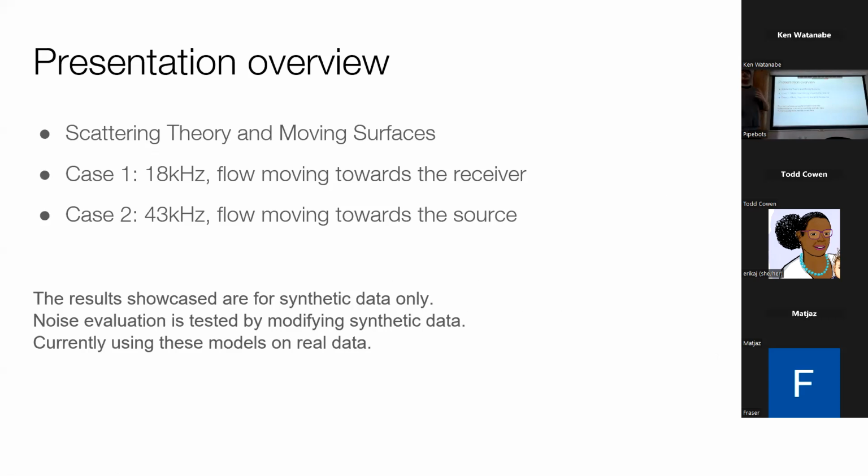So I'm going to peel back the H kernel and show a little bit of what that is. It's a big integral. And we have 2 cases. We've assumed in this whole thing, for simplicity, that it's 2D and we have a constant depth below and a constant average velocity, just to make things clearer. There's no reason why this wouldn't work with a variable depth. You'd have to be a bit careful. I know when you're using the ADCP with photogrammetry, you want to move around your beams, so you'd have to be a bit more careful with the way you move it above the surface.